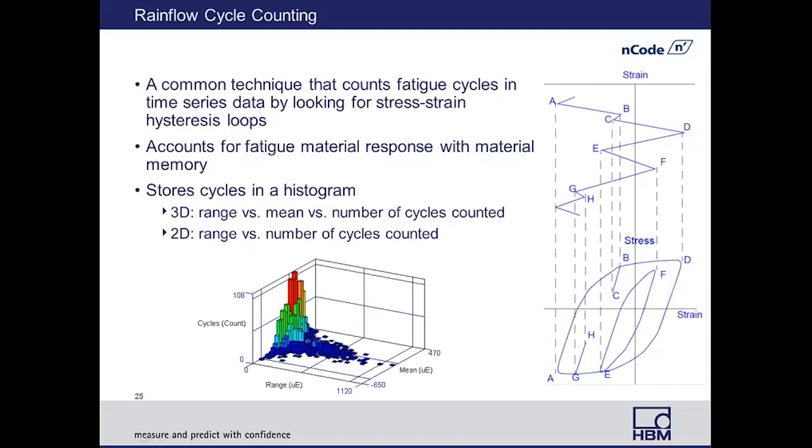So we have gotten into the region where we have a nonlinear relationship between stress and strain. But at B, we then drop the level again to C. So that drops and creates a small cycle right here. So BCB is going to be a small cycle. And from C, we then continue onward up to point D.